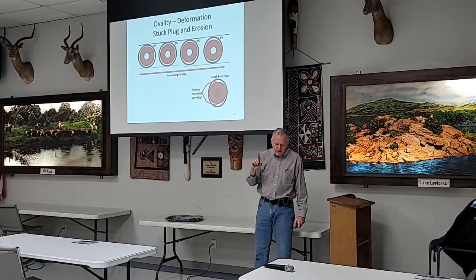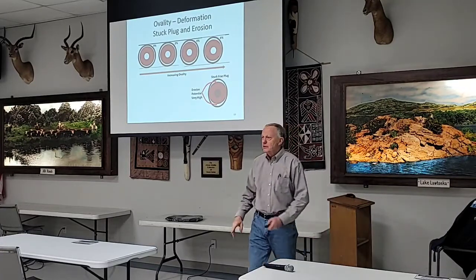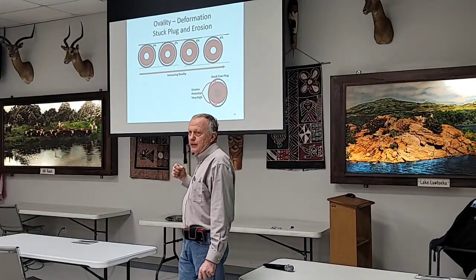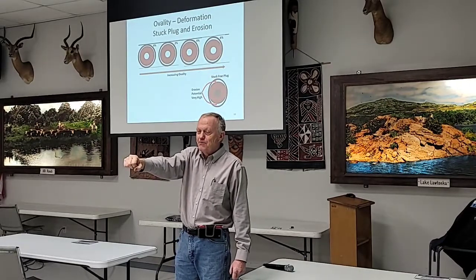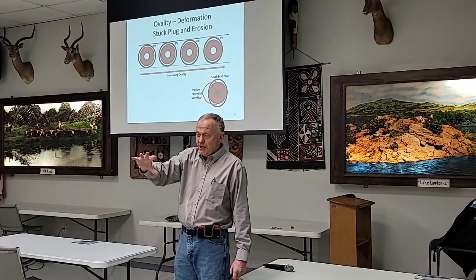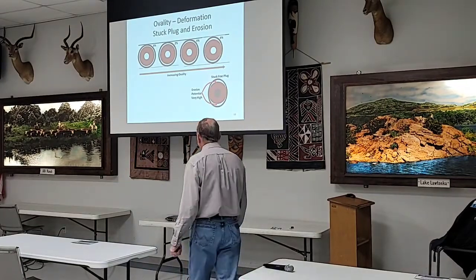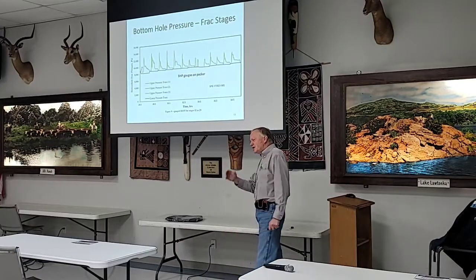Please don't, there's one thing that we see time and time again at Viking. They'll have a problem, they can't get the plug down, they'll pull it out, and they'll run in with a mill, and they destroy every bit of evidence, and then you do have a breach or a leak in that pipe. So try to take care of it ahead of time, because the remedial actions from this are not big.